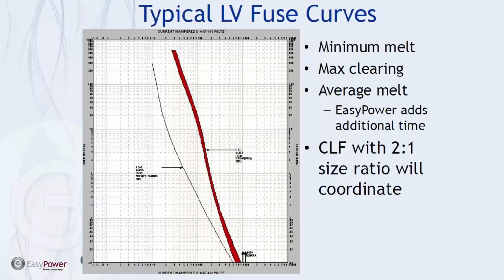And when we talk about the TCC curves, by convention, the bottom of the TCC plot is 0.01 seconds. Well, the first half cycle time is 8 milliseconds, so that's actually below the plot of our curve.